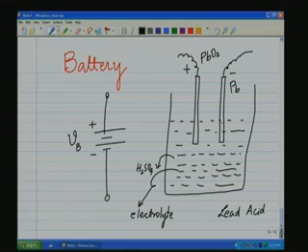The electrons get generated from the cathode, flow on to the anode, and from here to the external conductor, to the external circuit, then back again to the cathode. And in the process, as far as the lead acid battery is concerned, water is generated and it dilutes the battery and the charge goes down. So, repeatedly as the charge goes down, you will have to recharge the battery again back to its original capacity, which means the concentration is brought back, and then again it is in the charged condition.